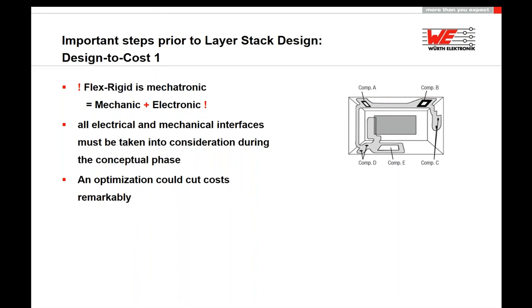to do this. For example, in Cadence, for this you need the professional version. That's not included in the basic version of the Cadence tools. You have to do the definitions for the materials and the layers. Of course, you will have flexible materials, maybe a flexible solder mask and polyimide cover layer for the flexible areas.